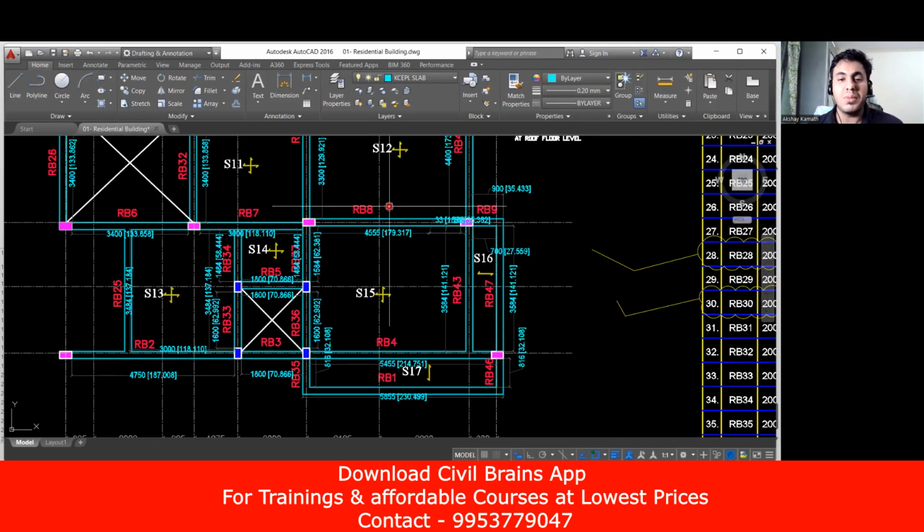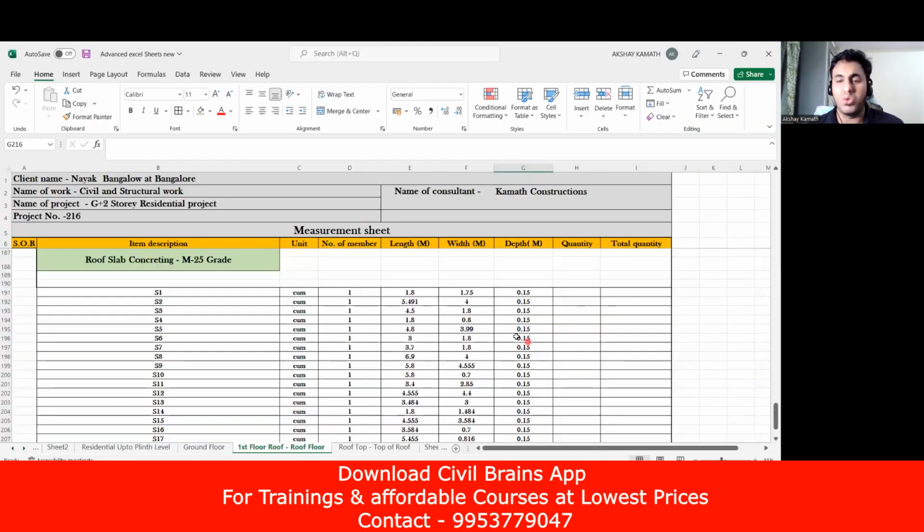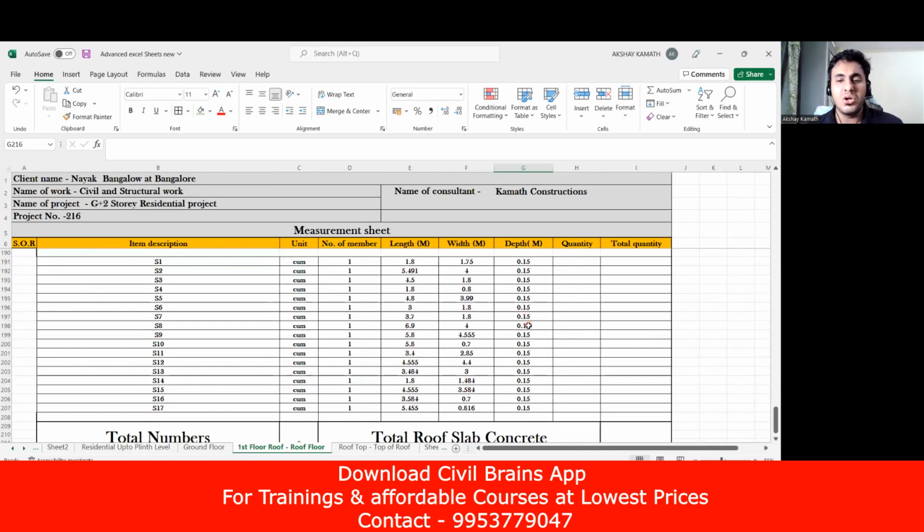Otherwise, you may make a mistake. That is why first you write down all these things, whatever is necessary for you. You can even write it here itself. If you find it confusing, just in case there is a variation, write in front of S12 150, S15 it is 175, S17 let us say 200. In that case, when you do the input in the Excel sheet, you won't go wrong. But luckily, in our project, all my slabs are 150, so I write 0.15.